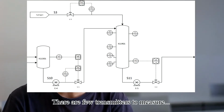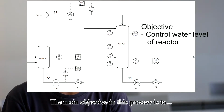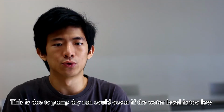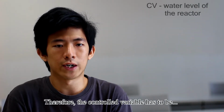There are a few transmitters to measure pressure, temperature, and level. The main objective in this process is to control the water level in the reactor. This is because pump dry run could occur if the water level is too low, and it could lead to process upset as well as pump damage. Therefore, the control variable has to be the water level of the reactor.